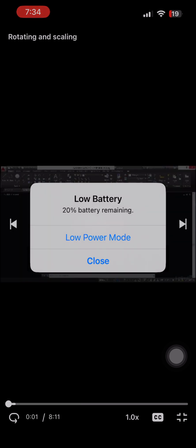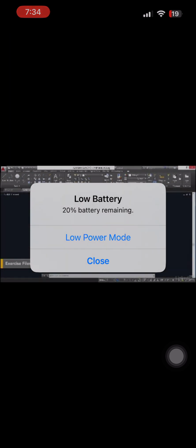In this video, I'll discuss the rotate and scale commands. Open the architectural sample file and zoom in here into this room by the fireplace. Let's begin by rotating this chair. Click the Rotate tool here on the Modify panel. You have a Select Objects prompt. Select the chair and press Enter to exit out of Select Objects mode.